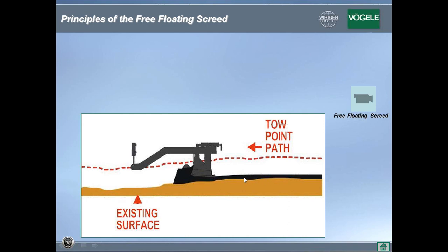So as the front wheel goes into that short undulation, of course, your toe point will try to drop. Your toe point will get thinner, so the angle of attack will reduce momentarily. But because it's only a short undulation, there's not enough time for the screed to react, so it fills that low point. Likewise, for a high point, as the wheel goes over that high point, the toe point position will go up, increasing your angle of attack. But because, again, it's a short irregularity, it's not 3 to 5 times the length of the toe arm, there will be no change.